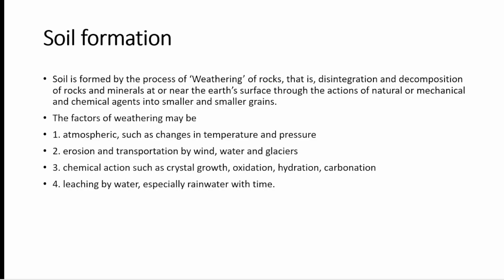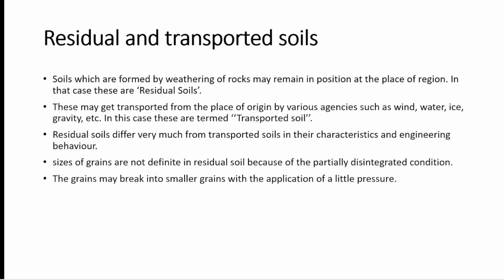Harder minerals will be more resistant to weathering action, for example, quartz present in igneous rocks. But prolonged chemical action may affect even such relatively stable minerals, resulting in the formation of secondary products of weathering, such as clay minerals like illite, kaolinite and montmorillonite. Clay mineralogy has grown into a very complicated and broad subject. The last topic of this video is residual and transported soils.